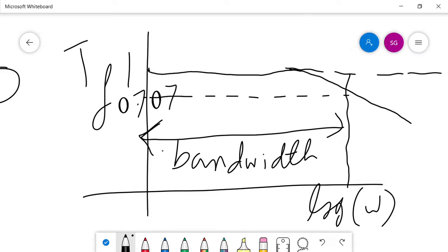So as input changes, the transfer function should be higher than 1 by root 2, that is 70.7% of the input. If output is tracing the input up to 70.7%, then we can treat it as a good response. So we can consider that to be the bandwidth. So we need to design our control system to achieve this bandwidth.